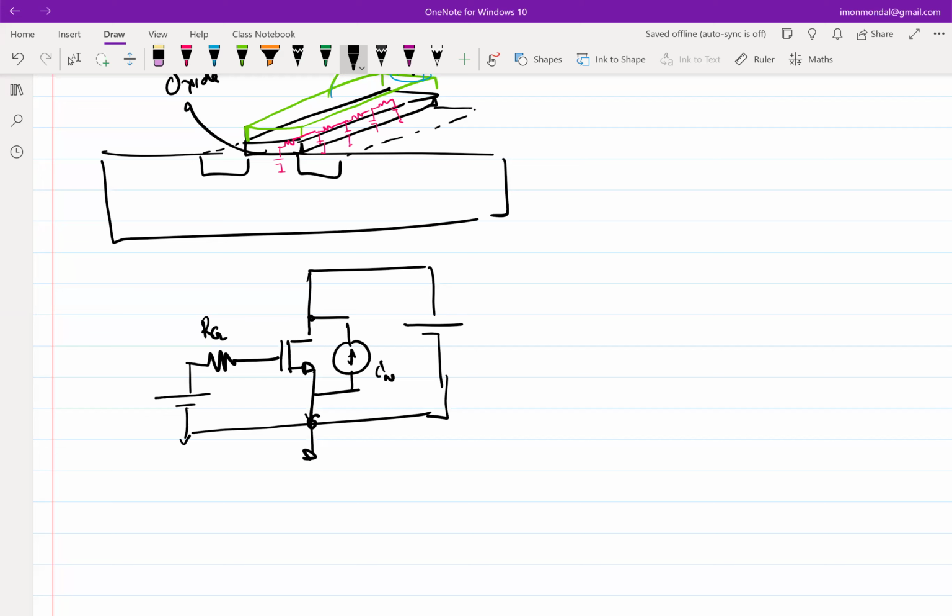By the way, noise is always a small signal current, because we are not expecting wiggling which is higher than that of your signal. Otherwise, your design is useless. If it is there, you have to somehow make it smaller. The moment you make it smaller, you can use all the small signal approximations. So when you do small signal approximation, you can replace the transistor with a small signal equivalent and do all your analysis about noise. That's a good thing about noise analysis, all small signal.